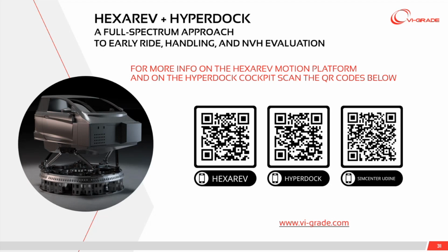Okay, cool. We've got a question here. Someone is asking, what frequency range is possible for this full spectrum approach? So the full spectrum, as shown in the first slide, we are talking about from 0 to 20,000 Hertz when we are also considering the acoustics. If we are talking about, let's say, the perceivable tactile vibration, we are talking about from 0 to 150 Hertz, more or less.